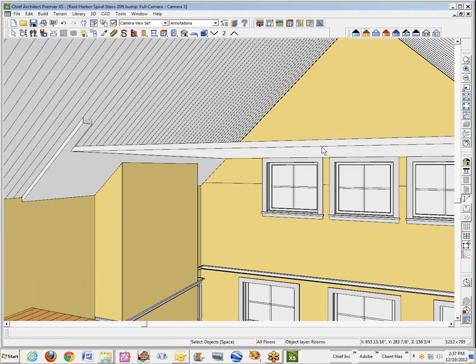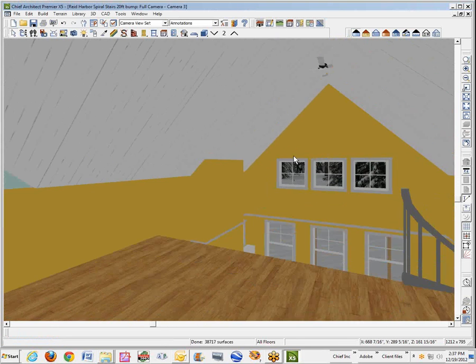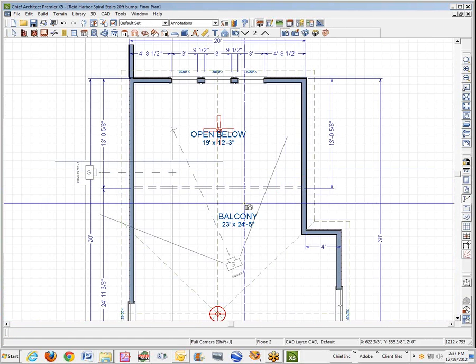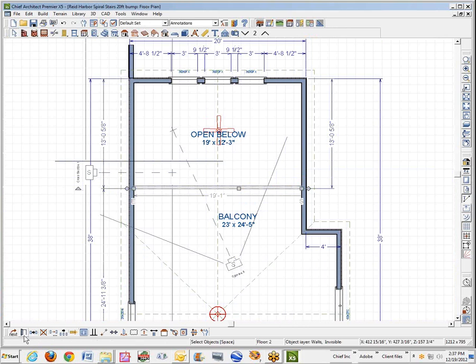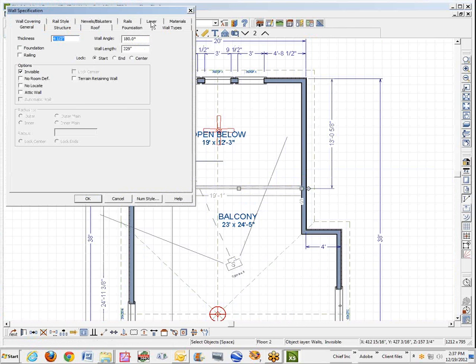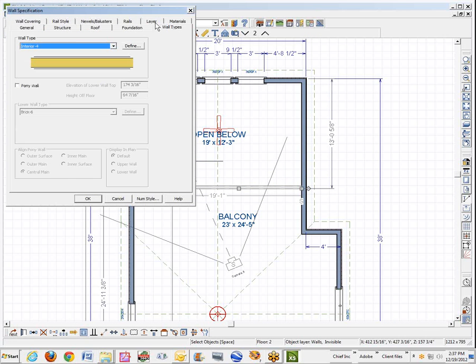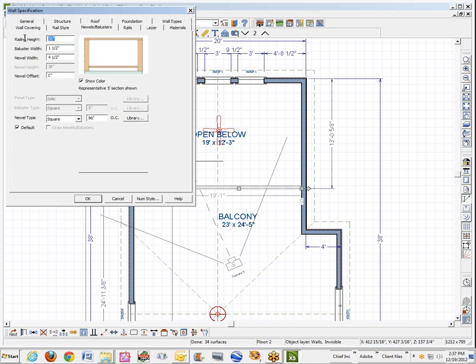Now in vector view cameras, it's going to show up, but see, in rendered cameras, it's now gone. Yeah, this needs to be something other than an invisible wall. It needs to be a railing, not invisible, railing. Where's newels and balusters? Yeah, it needs to be 42. That's the current code. And probably, I don't know if you can alter this in essentials or not.